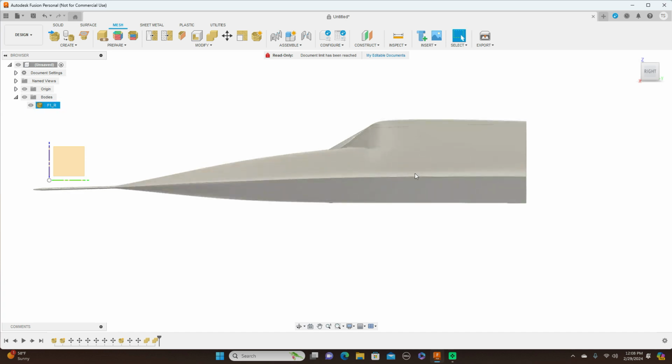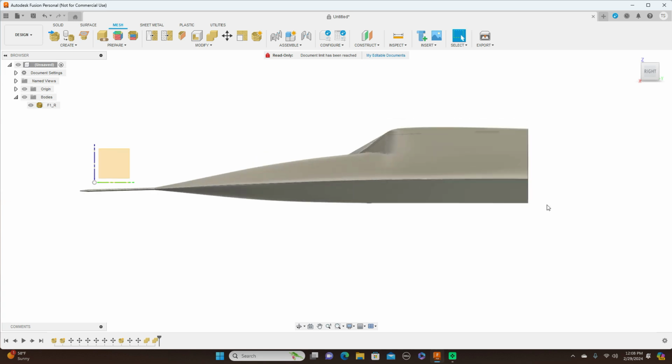And so when you split your box of the mold to have a top and a bottom, you would have a straight line, and some of this bottom mold would be in the top, and you wouldn't be able to pull the part out of that mold. So I'll show you how to get around that, to split this so you can do it properly.